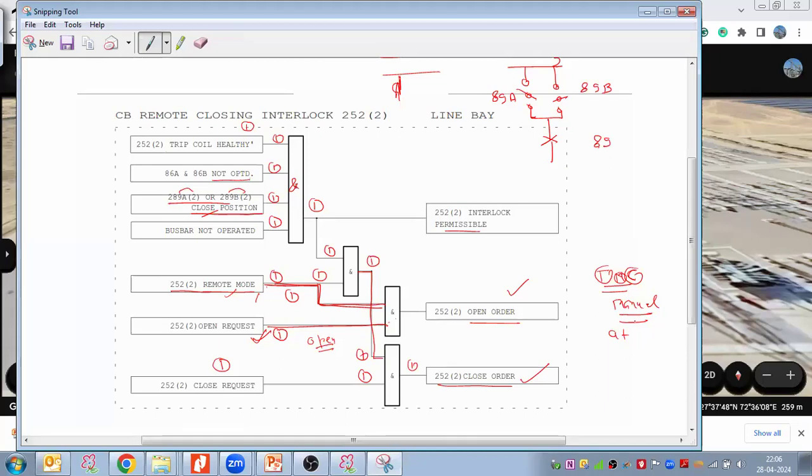That I understand. That's right. But when we are checking the logic, how is it being satisfied? Sir, I am answering that question. The logic is only for the BCU operation, not for manual operation. These interlocks are all for the local remote mode operation, not a local operation. So Rahul, whenever you are operating in the manual mode, your BCU is bypassed altogether. You have to do the equipment level control. You can't do anything through the BCU or SCADA or anywhere.